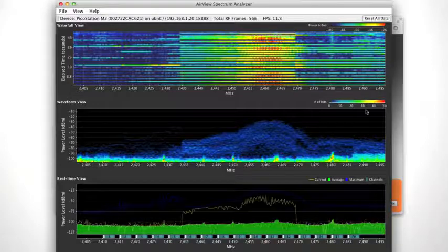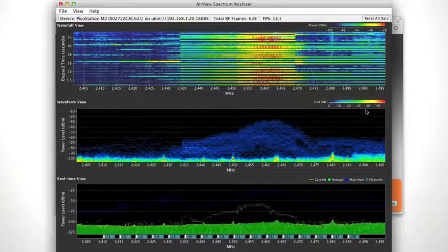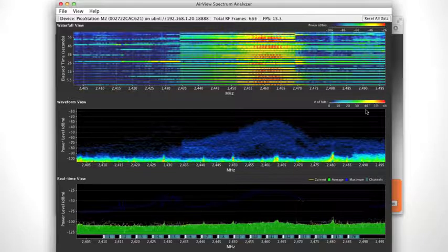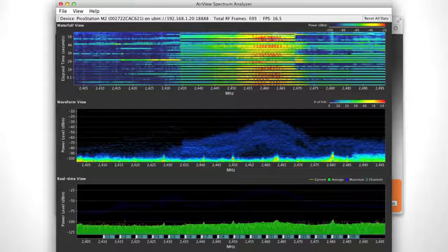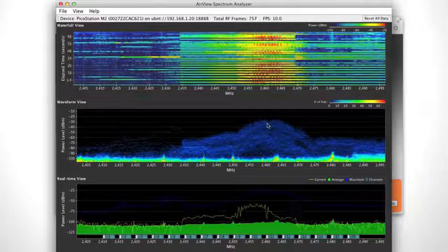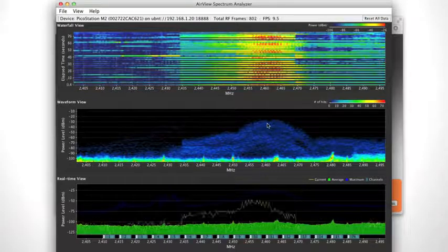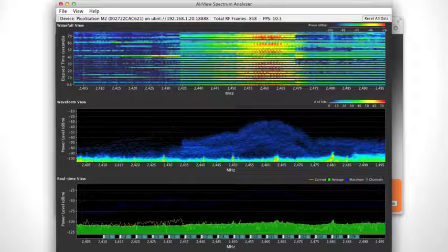One of the most fascinating aspects of this spectrum analyzer is that operators can examine the RF energy to determine sources of interference on the spectrum. For example, around channel 11, we see a lot of RF energy in a volcano shape. This shape is not unique to Ubiquiti radios only, since just about any OFDM radio will have a spectrum mask like this.